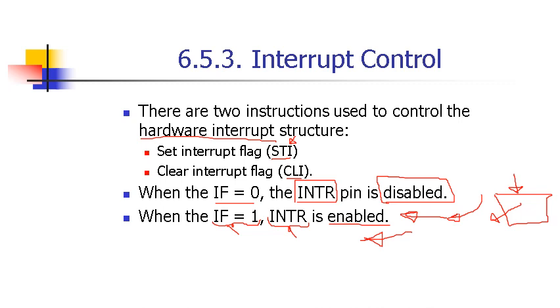So now an interrupt is called by hardware, the address is provided by your control unit, so your system will stop the currently being executed code and handle this interrupt service routine. All right.